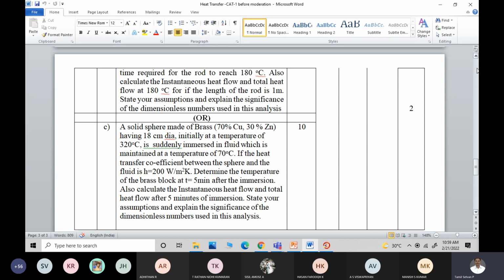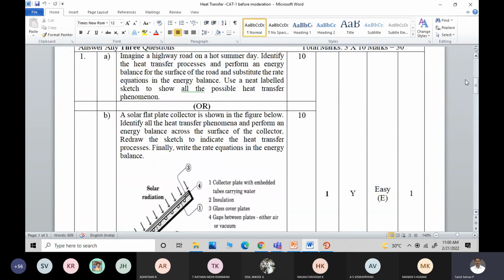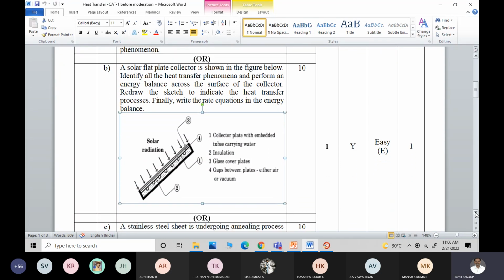Finally, coming to the first one. Now, the second one is very simple. The diagram was also given. The only thing is the solar radiation. Heat radiated is equal to heat conducted plus heat convected. Usually we know that radiative heat transfer occurs when there is a source at a very high temperature and a receiving body at a lesser temperature, and Q equals sigma A T^4, or sigma times shape factor times area times the difference between the two bodies, T^4 minus Ts^4.